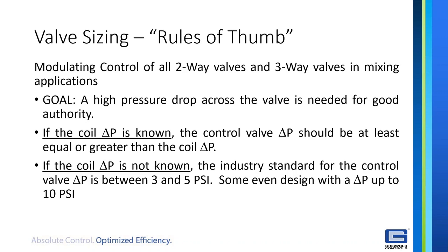As it goes through the smaller port and vaporizes, it can make noise and it can damage the valve. If the delta P is too high, then the outlet pressure may be lower than the vapor pressure, and then you're more at risk. So a conservative guide is to allow your pressure drop across your control valve to be less than half of the inlet pressure minus the vapor pressure. That's in our sizing guides, where we publish that formula.